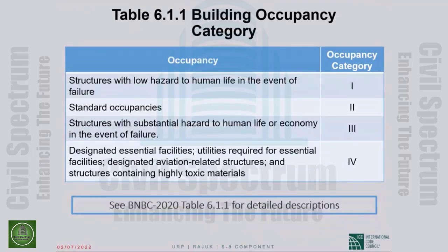Back in those days, the zone in which a structure was located determined the height limits for a structural system, like bearing wall systems could not be taller than 160 feet in seismic zone 4. The zone determined the level of analysis you had to do as the basis of design.